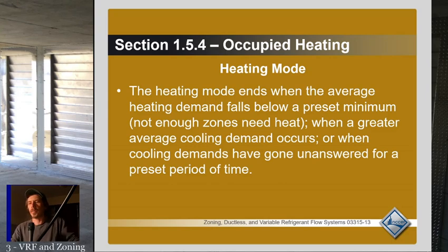So in a commercial VAV system, for instance, a lot of times the only zones that have heat are the zones that are actually on an outside wall or ceiling, right? And then all the zones on the interior will be cooling only, because they only experience heat gain, they don't experience heat loss. So on a VVT system, especially if it's a larger one, it could be 20 degrees outside and you've got a lot of zones calling for cooling. So heating is usually going to take the back seat to cooling.